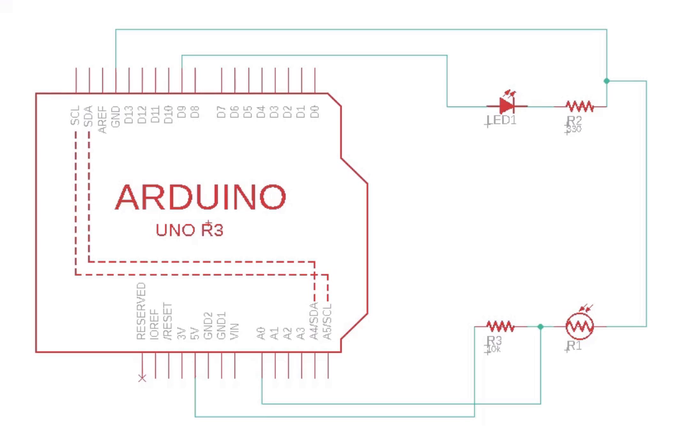This reversed configuration will instead light up the LED brighter and brighter the darker the photoresistor currently is. So, even this sort of mistake that had me tearing my hair out and wondering why it's not behaving the way it's supposed to, actually does have some practical use on its own merit, perhaps even more so than the simple circuit that we've been shown here in this example.